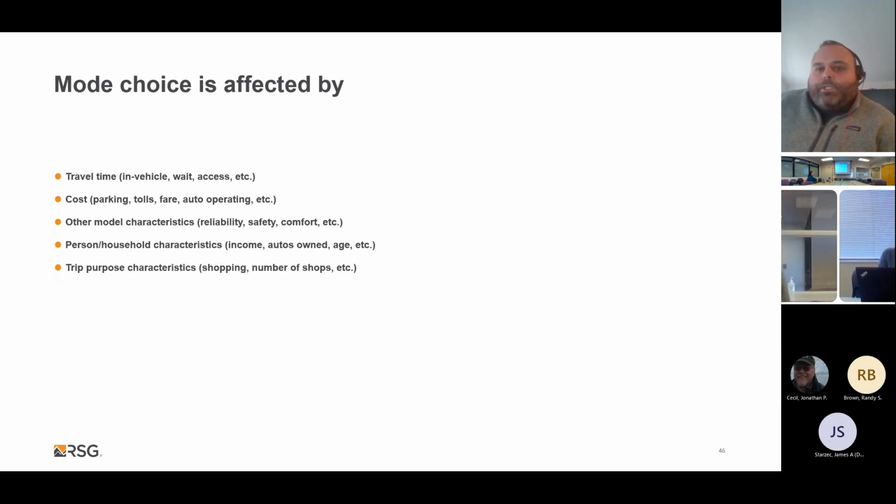It is too late to do that. And the other issue is that we wouldn't have a way to estimate with that information. So we need to think about the design of the survey and how the mode choice models are technically estimated, right? And that has to be accounted for in that stage. For example, the work that we did to sensitize the travel demand model in this phase of the update was to borrow, or transfer, parameters from San Diego, where they did similar work trying to capture land use and transportation interaction as it pertains to walkability and bikeability.